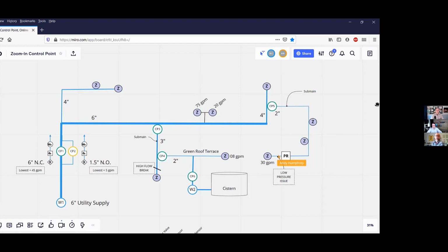And every time you run that one section of the system, you get a dramatic drop in dynamic pressure. Those are really hard to diagnose and really hard to find, even though your starting pressure is good. This can help you do some of that sleuthing and figure that out. You can figure out what was running at what time and what's going on.